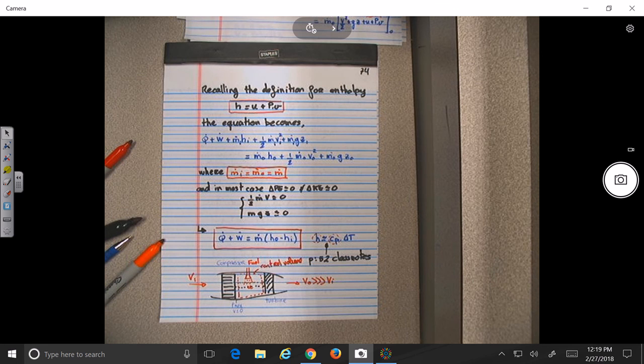So really, if you want to do the design of an engine, you need to think about what? You want to have a high pressure and high internal energy, no? So that means you want to have a high enthalpy, no? So I think that's the only logical reason I can think of why they came up with the term enthalpy. Because when you do the design of an engine, what you want to get is a high enthalpy. Instead of repeating every single time, I want a high internal energy plus high pressure, you want a high enthalpy. Which means what? You want to have a high pressure plus a large amount of internal energy.